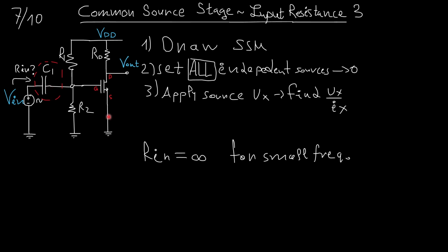It's important to understand that we use this topology because, right, we don't really cover this in this video, but we do it because if we had a short circuit here and the input voltage became for some reason zero, all of the current would flow through here to here, and we would not have a proper bias here. So this capacitance protects us from this.